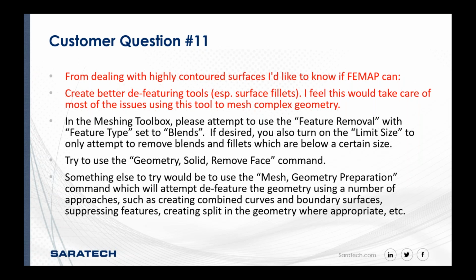If you just kind of want to try some brute force, we actually have the geometry solid remove face command. I mean, the toolbox is using this as well in the background, but maybe just picking which ones you want to try to get rid of, especially if it can't get rid of some, but it can get rid of others. You might be better off just trying iteratively to remove some faces.